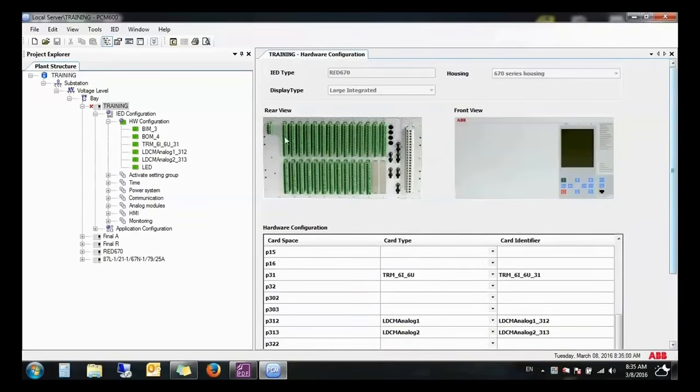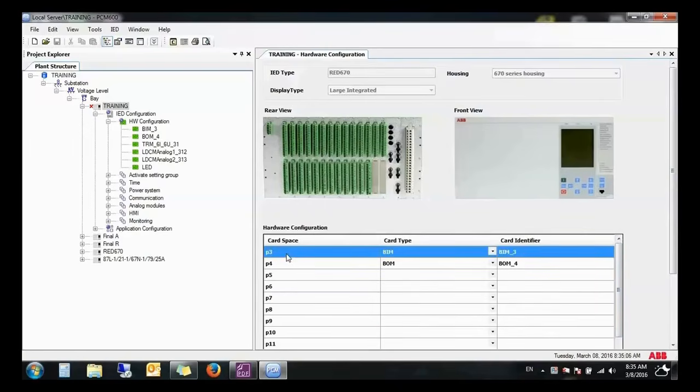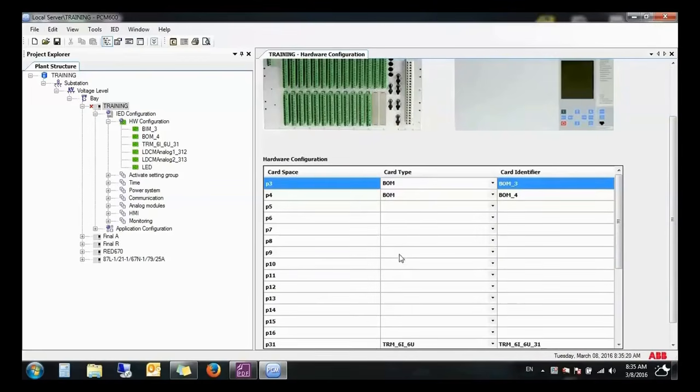As for the second set of cards, you will find that each card is designed for you. Or they have chosen a type for you, for example the card B3, where they have chosen a binary input module. This card can be replaced with any of these cards without any problem, but you have to think: if you change it here to a binary output module, the relay needs an actual binary output module installed. The idea is that all these cards can only accept these types.